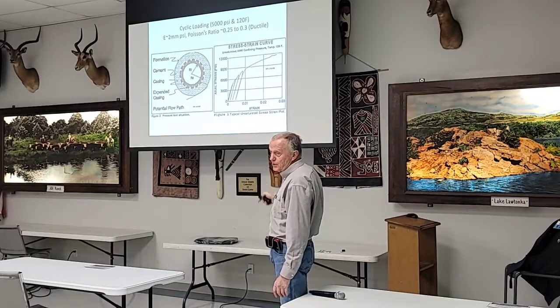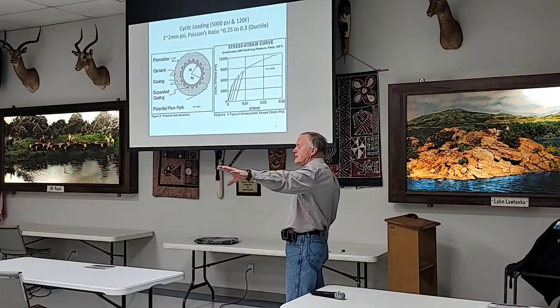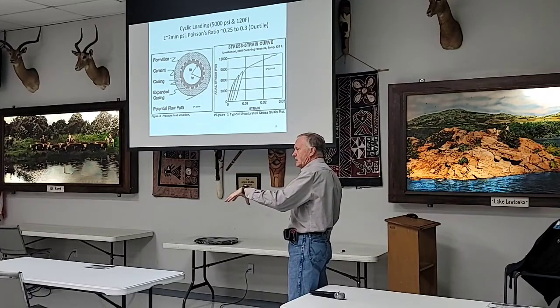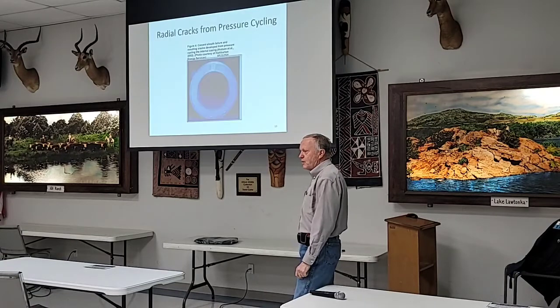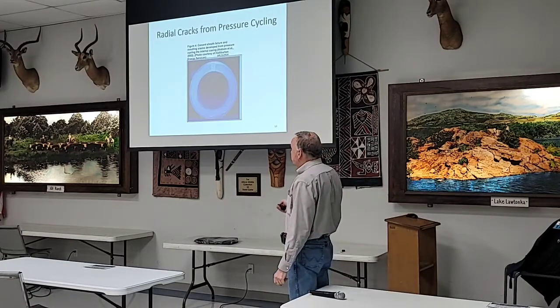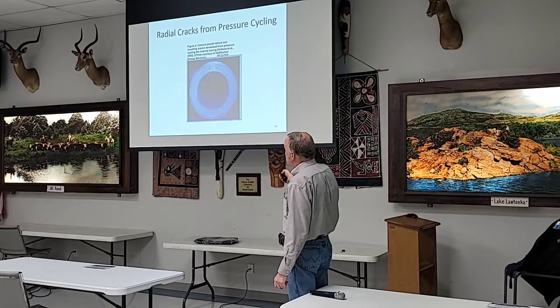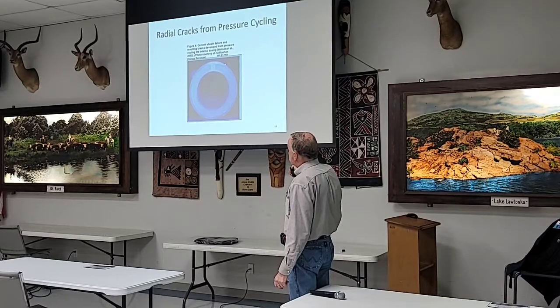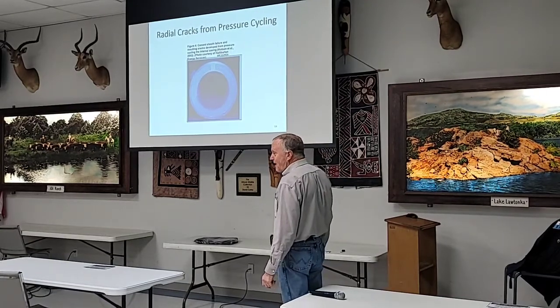There's a URTeC paper that we did on this that used the WellCat model, and the WellCat wouldn't even show it until they put a fatigue model in there. And that actually triggered the knowledge of what that's caused by. And hey, this was from 2002. This is not new. This is basically a Halliburton shot. And this is pipe, cement, pipe inside pipe, cemented up and then pressured up, it cracks the cement in there. So you are going to crack that.